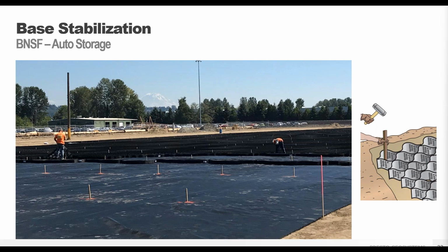Another technique tip important for large projects is to prep the site layout. This contractor wanted square panels for the entire installation, so they actually surveyed and staked the corners of each GeoWeb panel over the 25-acre site. Once the GeoWeb panels were filled, they just pulled the stakes.